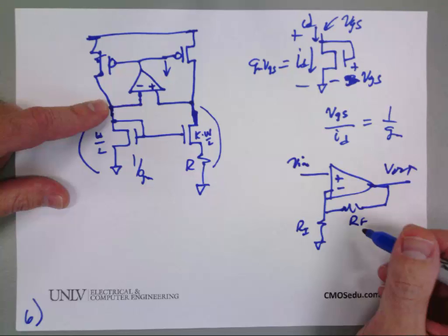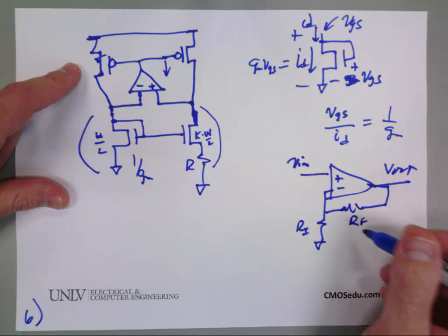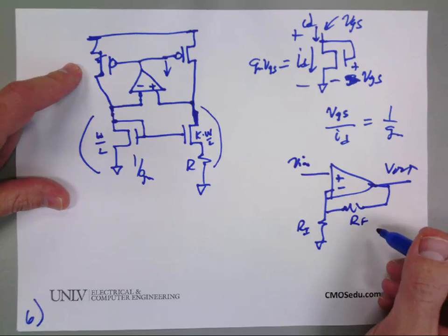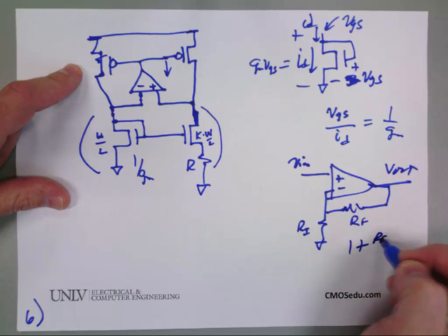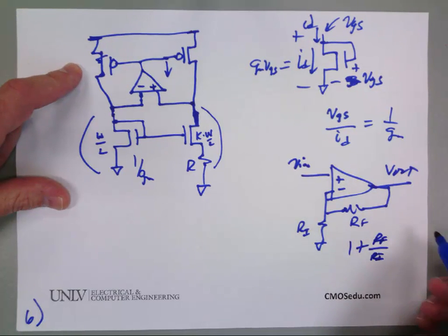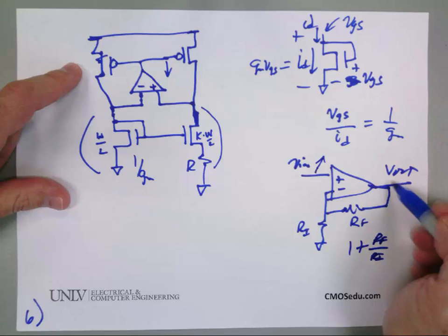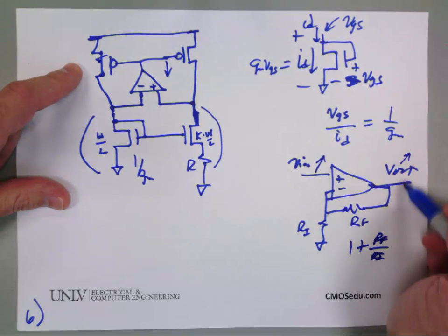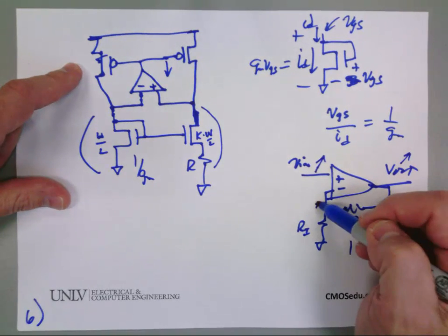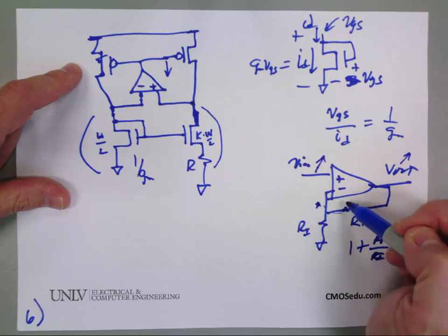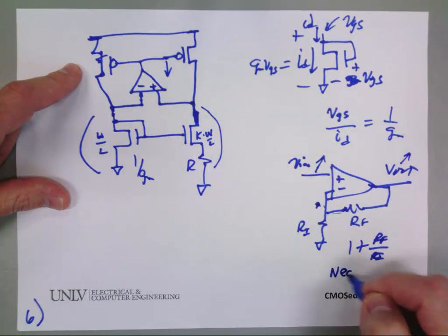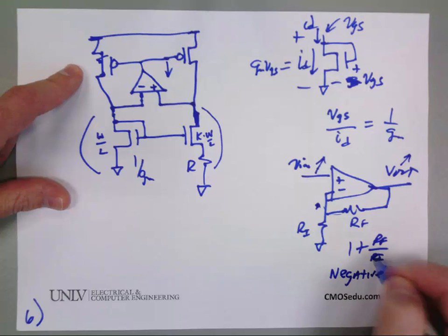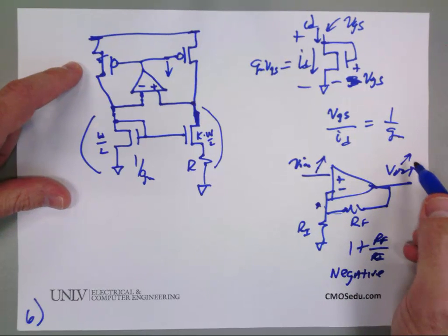What's the gain of this? Okay, so if this signal starts to go up, and then it feeds back around, and then this goes up and subtracts, this is negative feedback, and keeps the output bounded. So most circuits use negative feedback.